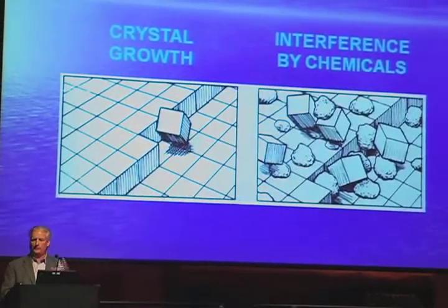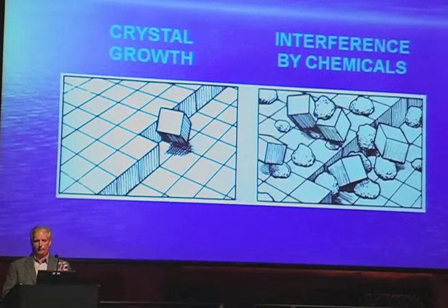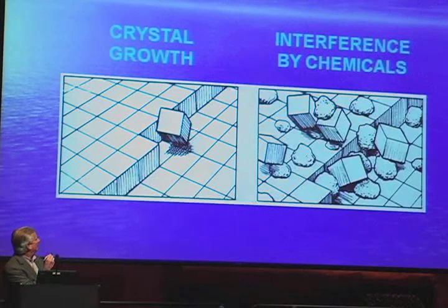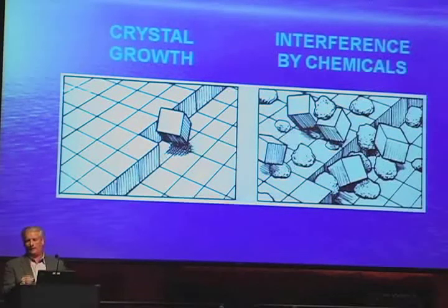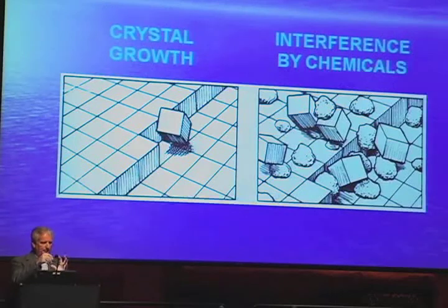And basically when calcium carbonate forms, it forms in a crystal, okay? And that crystal actually compacts, one on top of the other, forms nice layers, and you get a nice layer of scale formation. It's all usually pretty even. So it forms a nice compact, and they fit in nice little segments, and that's how you grow scale formation.